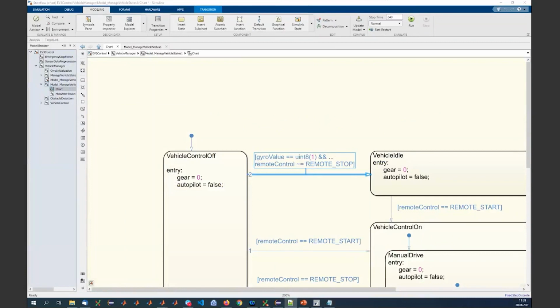So this is a failed finding, but there are cases of implicit typecasting in Stateflow where it is not possible to compile the model and which are getting identified by Simulink. But the problem for this use case is now that there are cases where it is not like this. So here we can still compile the model without any warnings from Simulink. And to avoid any problems in later stages of your software development or even in your final code, you can use this new check to early identify these implicit typecastings in Stateflow.